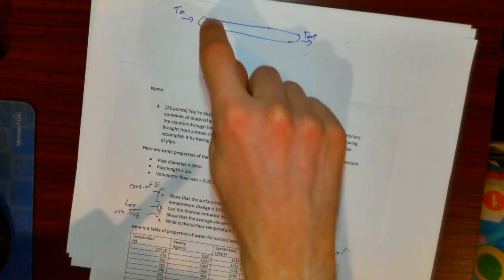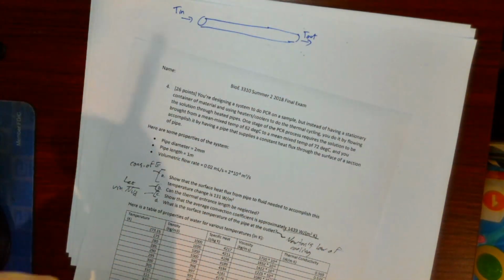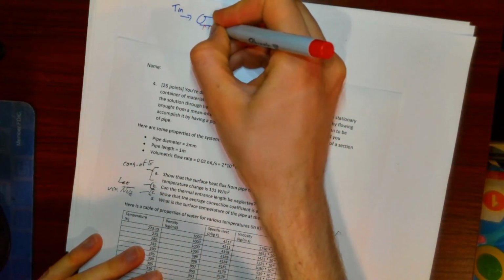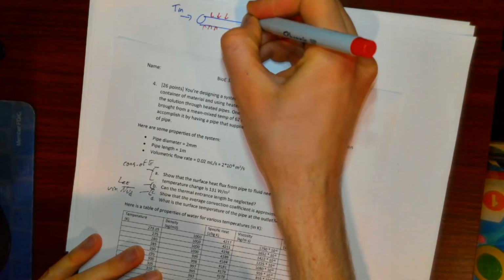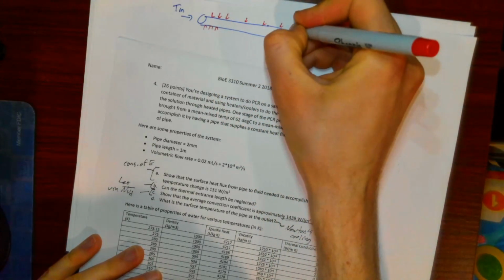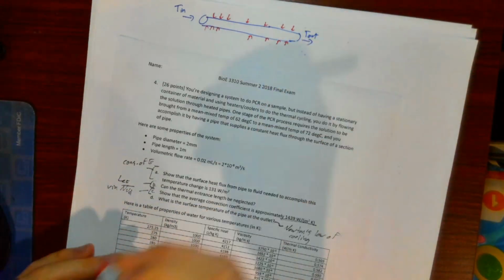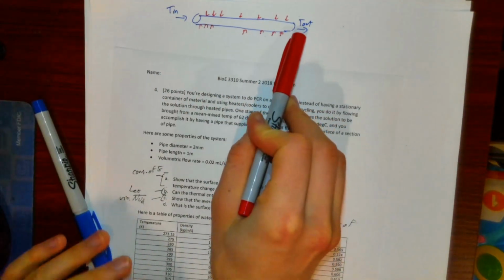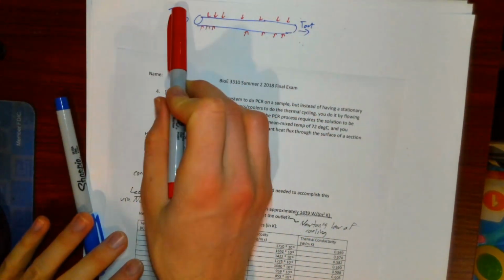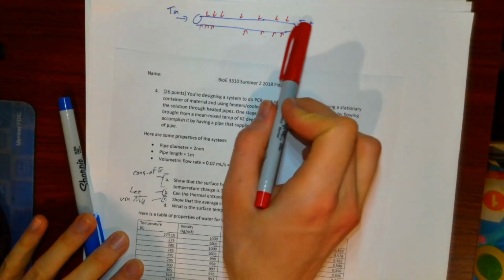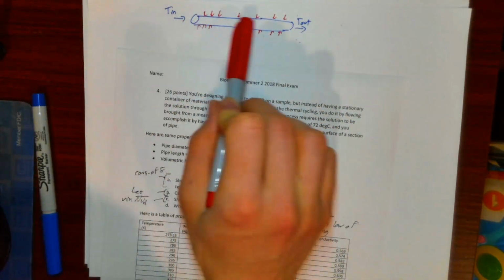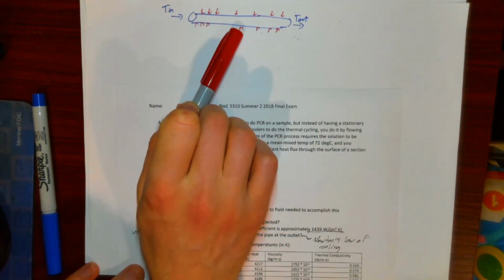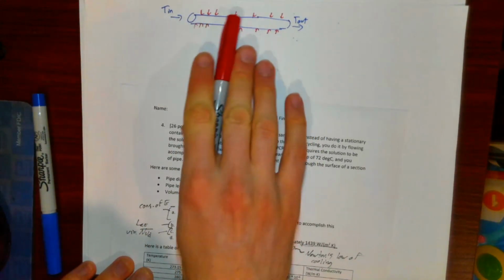And then we have this pipe, and this pipe is basically dumping heat into all of the walls of this thing here. So we essentially say, hey, there's some temperature of the flow going in and some temperature of the flow going out. We consider this as thermal energy carried by mass in, thermal energy carried by mass out. So the difference in those thermal energies carried by the mass must be accounted for by the power from all of the heat flux that's entering the walls.